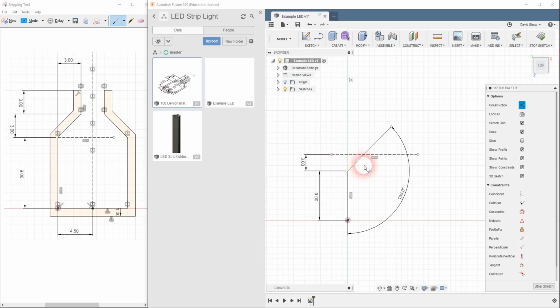I'm going to come to the trim tool, and I'm actually going to trim that line back, and now I've got an intersection at that point, and I'm going to trim that line back as well there. And now if I come to my line tool, it will actually snap to that point, which actually is much better. Now it's still construction. Let's turn construction off there. This is going to go vertically straight up another 3 millimeters. Well, I'll pull that back down to 3, right click, and OK there. So that's looking nice.